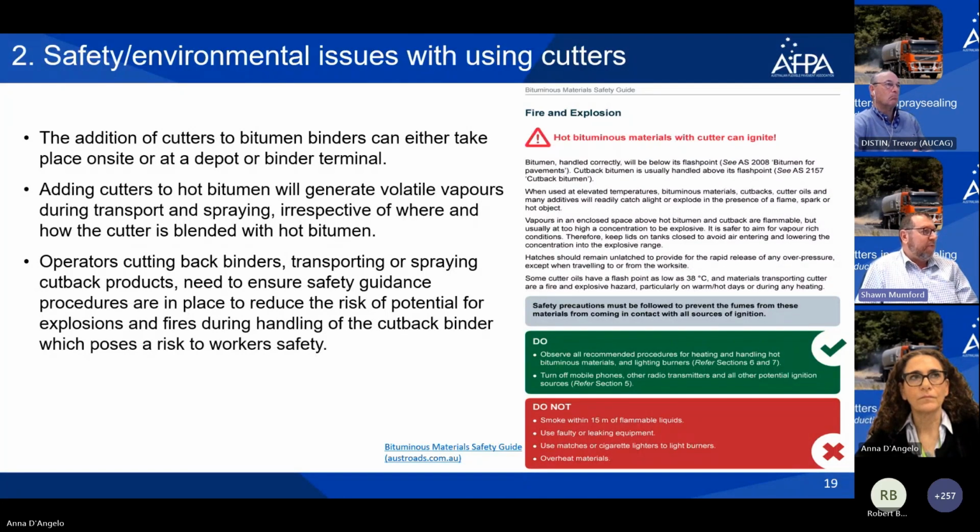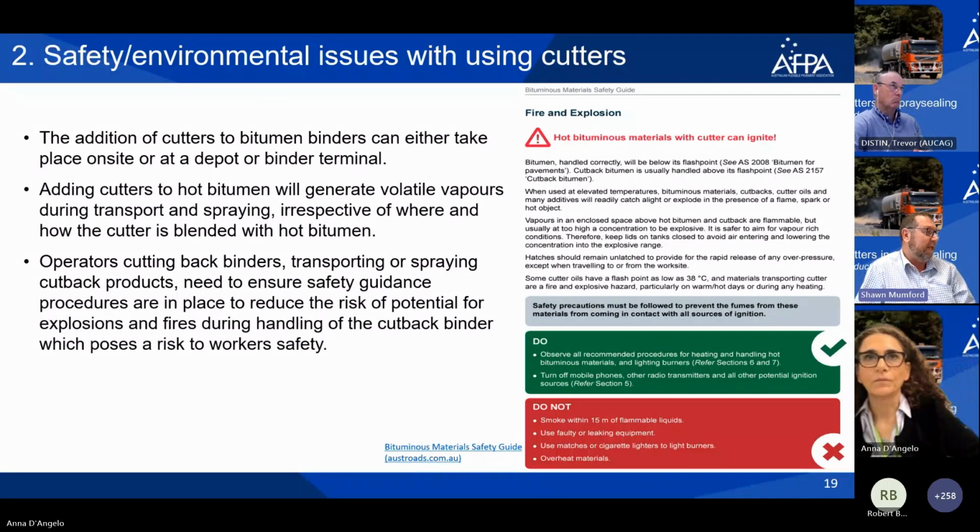Adding cutters to hot bitumen will generate volatile vapours. So during transport and spraying, irrespective of where and how the cutter is blended, you will get some of that volatile vapour that can cause the main concerns with fire or explosions around the use of cutters.